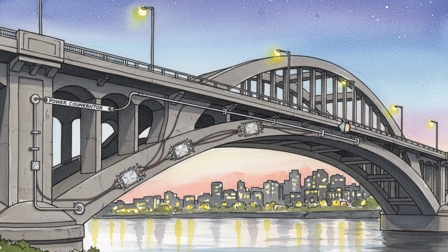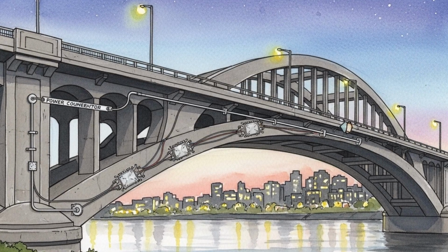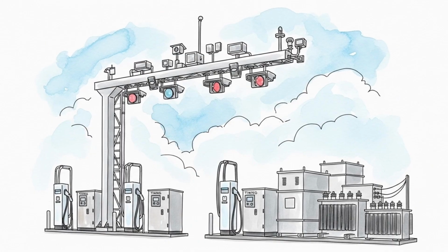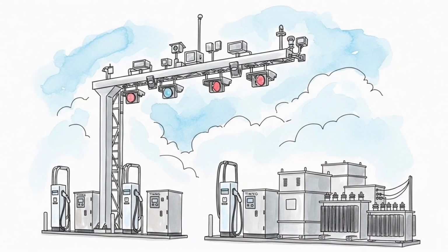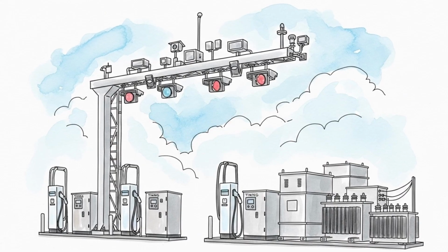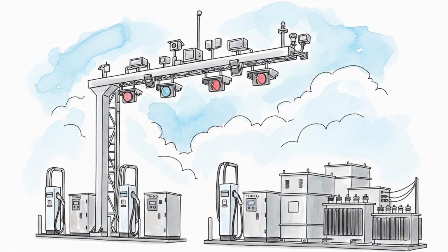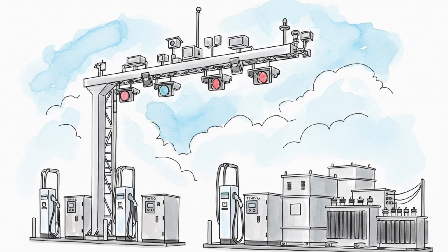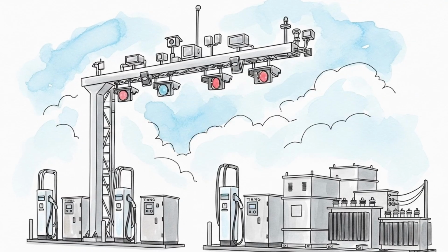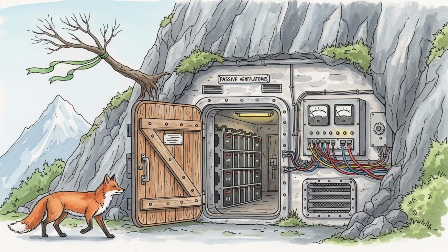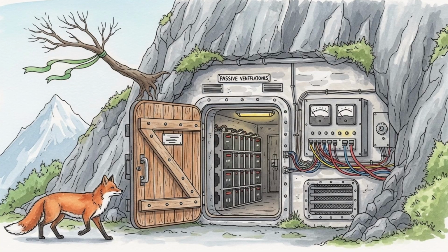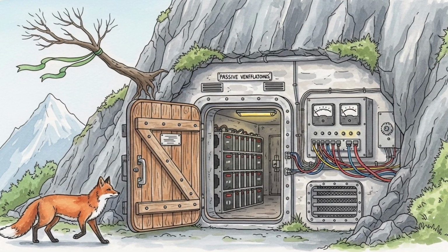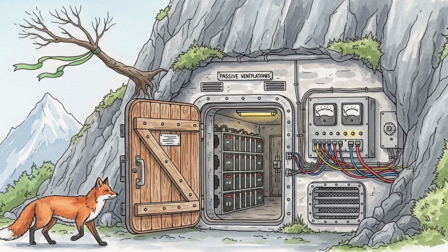Broadcast and public safety networks follow simple rules. If high-frequency service degrades, they switch to satellite or terrestrial line-of-sight links. If satellite beams at L-band show high fade or loss of lock, they select lower data rates and more robust coding. They maintain local recording and store and forward capability so that brief link outages do not remove critical announcements. Control rooms keep voice fallbacks ready and verify that paging and alert systems do not depend on a single timing source.